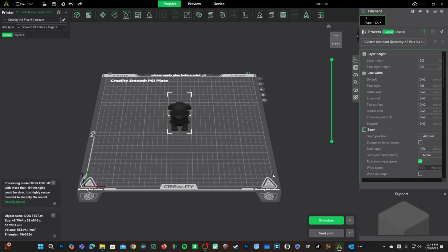In doing this, you may notice a warning about 1 million triangles. Models with 1 million or more triangles may be a little slower to work with. I have never encountered a situation where I have deemed it worth changing this. Simply disregard and press the X button.